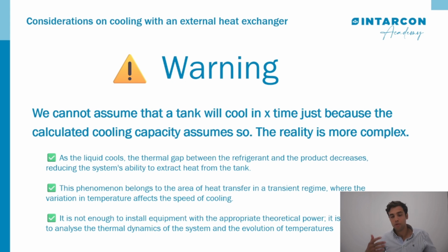It's not enough to install equipment with the appropriate theoretical power. As a consequence, it's necessary to analyze the thermal dynamics of the system and the evolution of temperatures. So we have to check the cooling capacity needs at the peak, and we also have to check the minimal temperature difference in the plate heat exchanger. Next, we are going to check it.